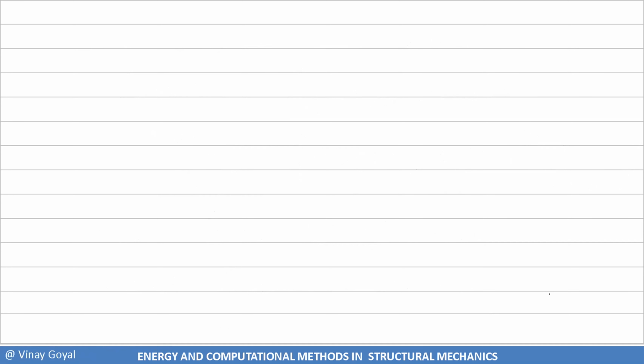Let's consider now the example of a bar with loading conditions and a spring. So example 3. I'll keep doing some examples so we can learn together how to deal with these problems. So EA u prime prime minus Ku plus f is 0. That's the governing equation, and it is valid between 0 and L.